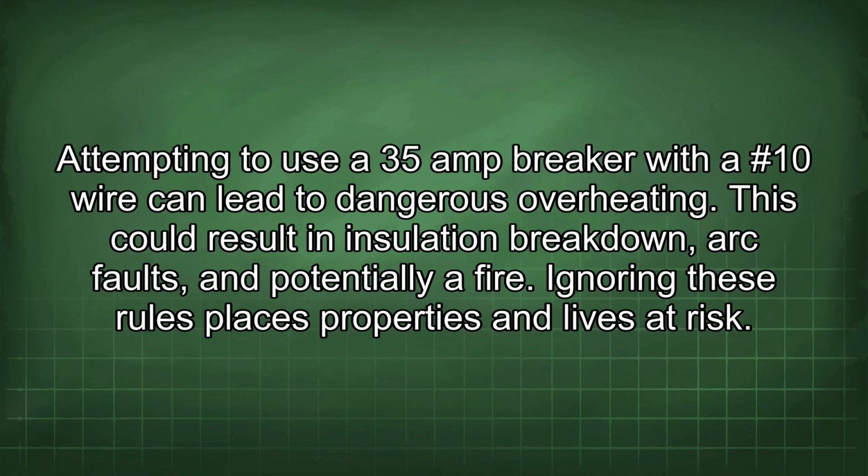Attempting to use a 35 amp breaker with a #10 wire can lead to dangerous overheating. This could result in insulation breakdown, arc faults, and potentially a fire. Ignoring these rules places properties and lives at risk.